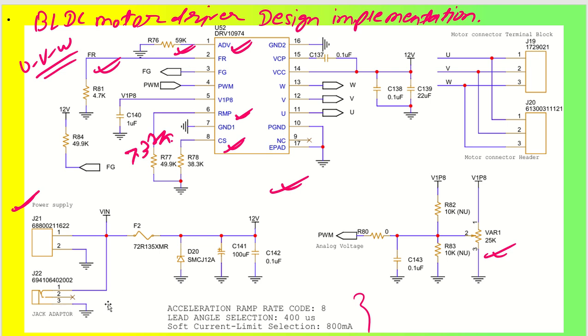If you want to power up this board, you have one more provision, which is the adapter jack, that will be giving you the input. To make it a much better circuit, you can utilize one diode here of, let's say, 2 ampere rating, of, let's say, 100 volt or 60 volt rating. So this one diode you will be able to utilize so that it can work.